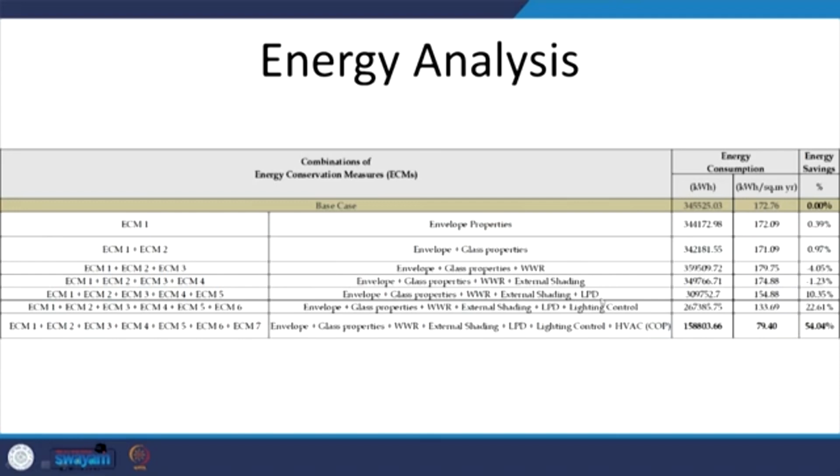LPD comes at a very reasonable price, it comes at a very little capital investment, and similarly lighting controls require a little more capital investment, but the percentage of savings that it brings along is tremendous, it is huge. So, we make a wise judgment of how much of energy savings will be brought in vis-a-vis the capital investment which is required for each of these energy conservation measures.